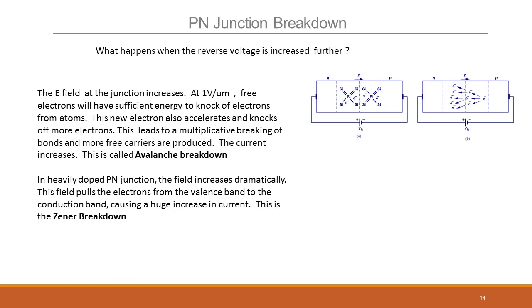Okay. So this is what we're talking about, silicon with a reverse bias. As you increase the reverse bias, electrons go and knock out more electrons out here. And these more electrons will knock out even more electrons. This is your avalanche breakdown. Okay.